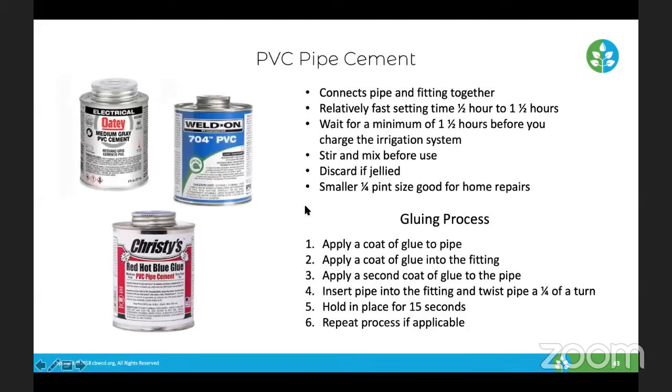Discard if it gets jellied. So if the glue starts to get kind of hard, it's not as liquid, just get rid of it. Get rid of it in the proper way. It is hazardous, so read the label to see how to discard it.